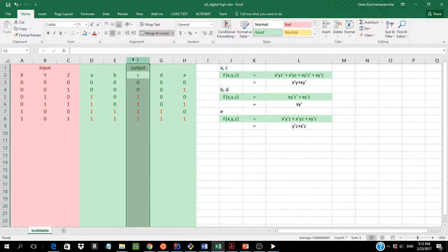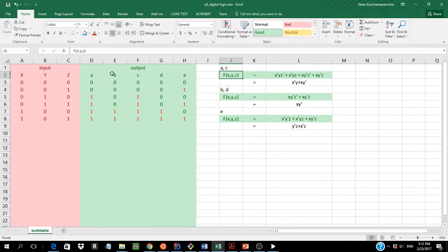You have 3 inputs, you get 1 output, right? Which is f(x,y) is your output. So that's why we have 3 expressions that we need, right? And some of them happen to be the same, so we can share it, right? Then we end up with 3 expressions. And from there, of course, you can do AND OR right away, but it's going to take forever and consume too much resources.